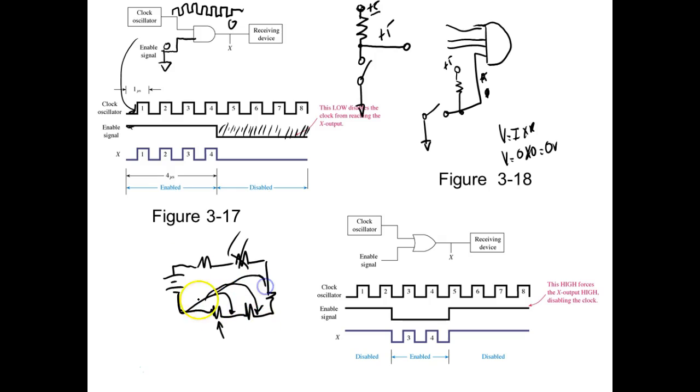That means this right here has moved right there. So if I measure across this resistor in an open series circuit, it measures the applied voltage. Why? Because nothing else in the circuit is dropping a voltage, because there's no current flow through it. So that's why hopefully you learn that in a series circuit, if you have an open, the entire voltage appears across that open.